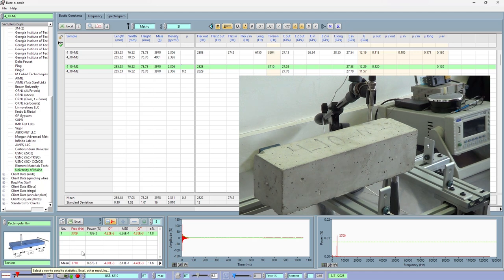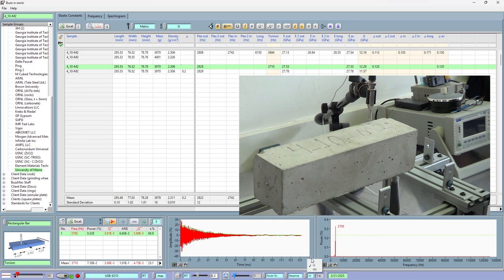Now, the other thing to note here, if we want, we could have offset this a little bit. You see, there's a bit of a sharp spike there. We can offset the waveform here to get a nicer curve. We could have also gone to, instead of 1 Hertz resolution, 10, and we'd have cleaned up the spectrum that way. But I think we'll leave it on 1 for now. So if we go back to all these, you see that first initial spike there. It looks like it's picking up some noise, so we'll just do this to all of them. It doesn't really change the results that much anyway. But anyway, that's what we've got.